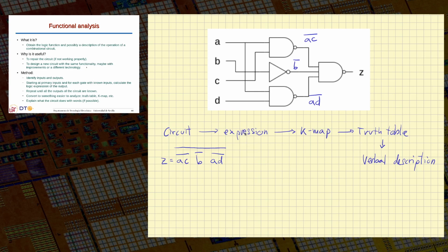So to move this expression to a Karnaugh map and to a truth table, we have seen in other examples the best, the easiest option is to write it as a normalized expression, as a sum of products or as a product of sums. It's easy to do if we simply do the complements. Okay, I eliminate the complements by applying De Morgan's theorem.